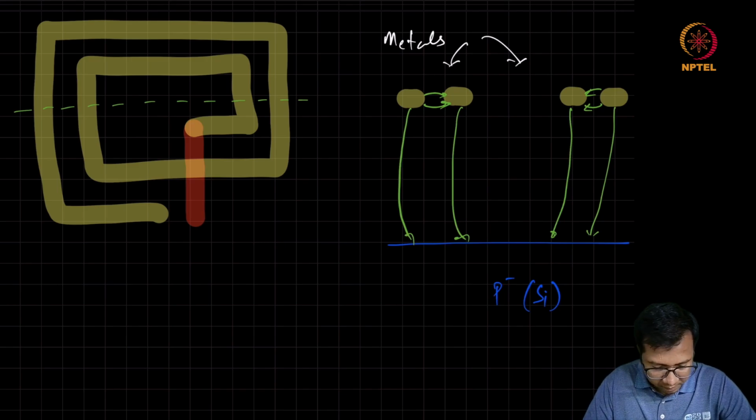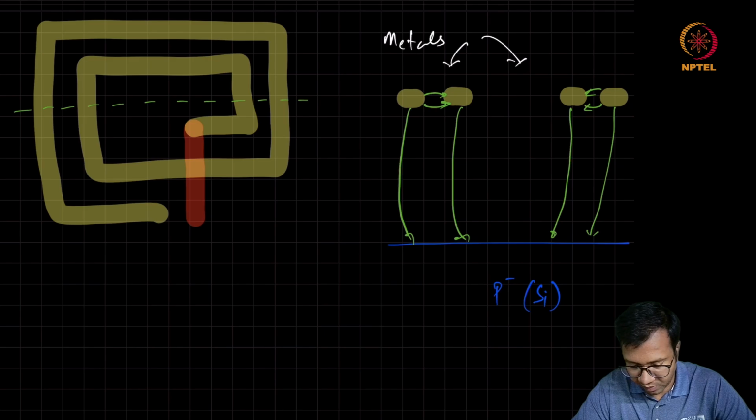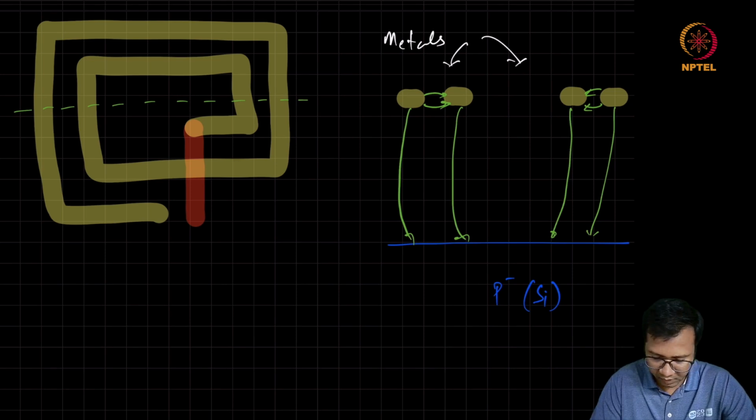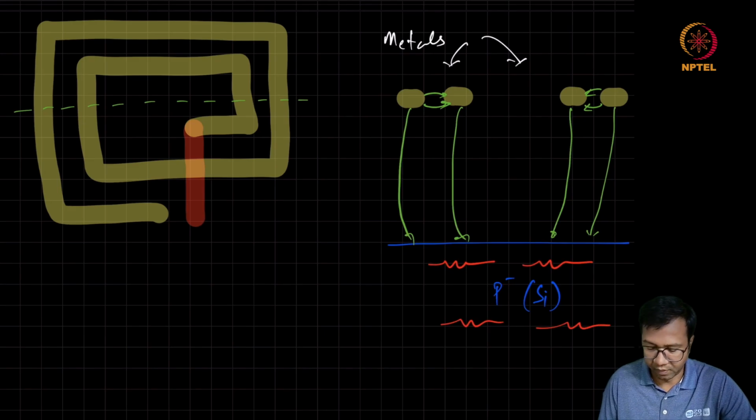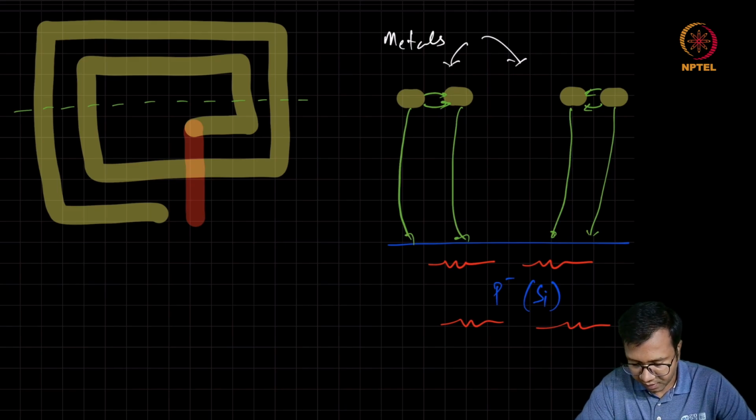So this inductor, which we are expecting to act like a perfect inductor, will have these capacitances present in addition to the overall inductance, and this capacitance at some frequency will resonate with the inductance, and beyond this frequency the inductor may start acting like a capacitor. And in addition to that, this substrate will also be lossy. The substrate can be modeled as a lossy dielectric.